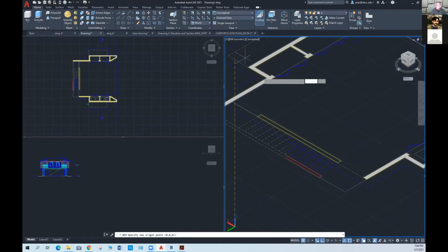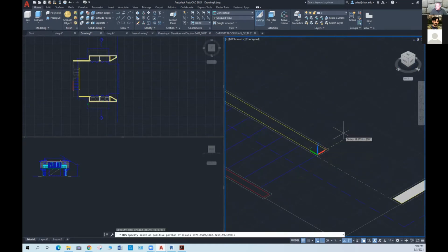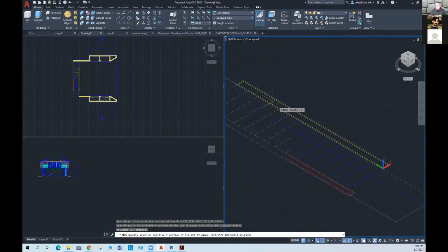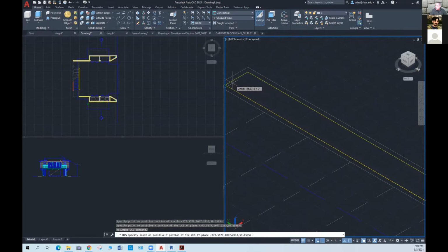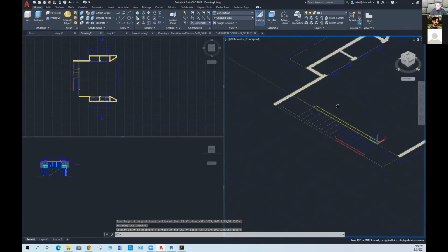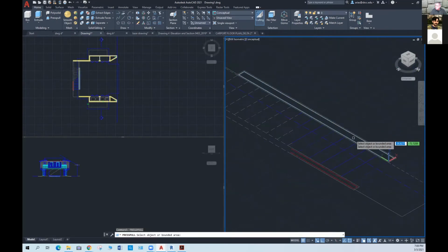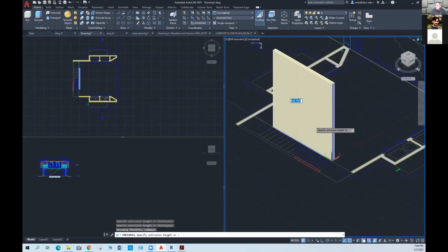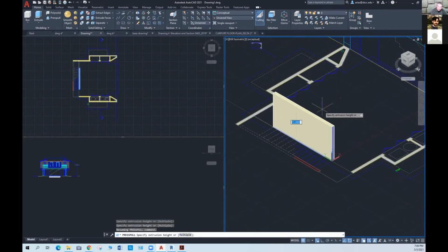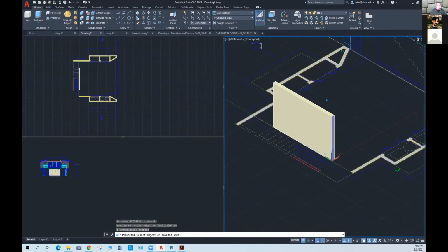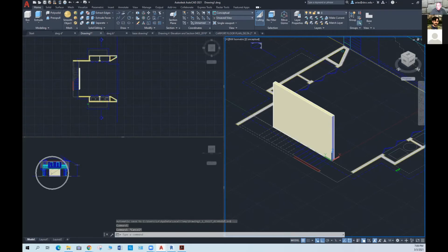So I'm going to select 3-point UCS, click here X and Y. And now let's do press pull. Really close to that. And now you have this object. That's the wall that we want to create. We're going to create that wall to be 8 feet. 8 feet is 96 inches. I don't have the inches yet, so done, right? And so see how it gets created here, but you see it here and you see it there.